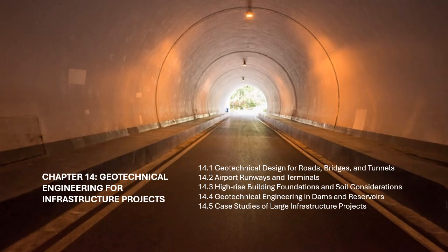Groundwater control. In many tunnel projects, groundwater can pose significant challenges. Groundwater ingress can increase excavation difficulty, cause erosion, and weaken the surrounding soil or rock. Geotechnical engineers assess the groundwater conditions and design appropriate methods for controlling water inflow, such as installing dewatering systems or using grouting to seal the tunnel walls.